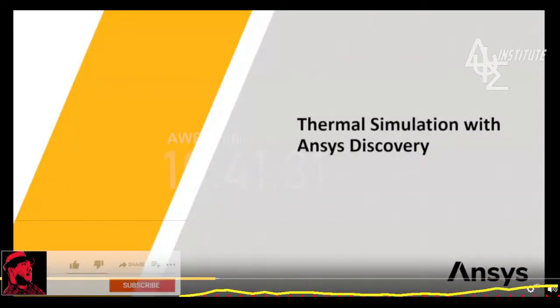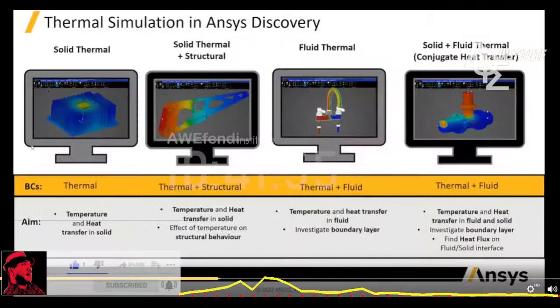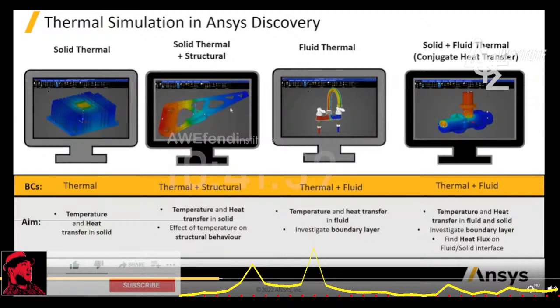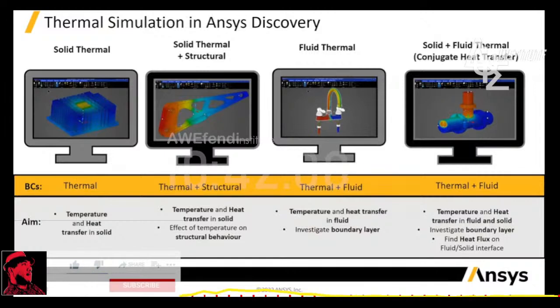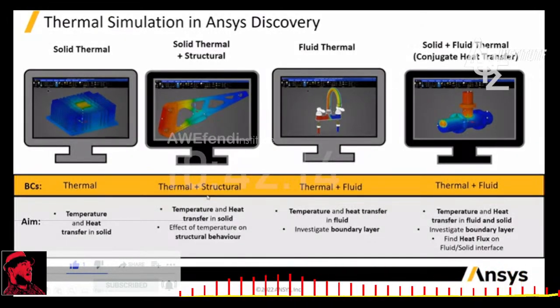So in the next 20 minutes or so, I would like to show you a bit of the thermal capabilities. We can not only get the temperature in the solid, but also check the effect of the temperature on the structural behavior. So Mario was demonstrating structural analysis. You can also add some temperature boundary conditions there and see how temperature affects the mechanical properties, because we support some temperature dependent mechanical properties as well.